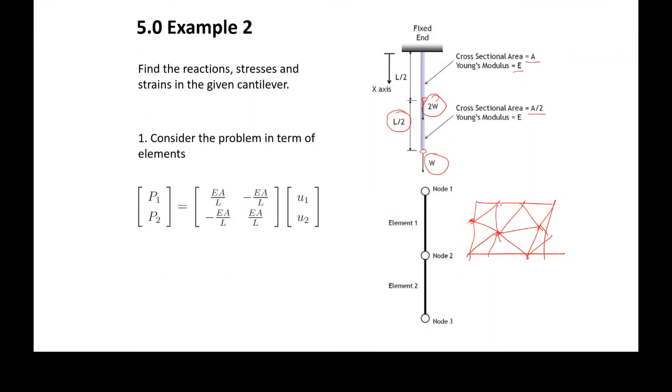And then basically these elements will meet at the nodes. And these nodes will have numbers, just like node 1, 2, and 3. You will have 1, 2, 3, 4, up to the last node. And then you need to basically build the stiffness matrix for each one of these elements, basically build these expressions for each one of these elements, and then assemble them into the big problem.